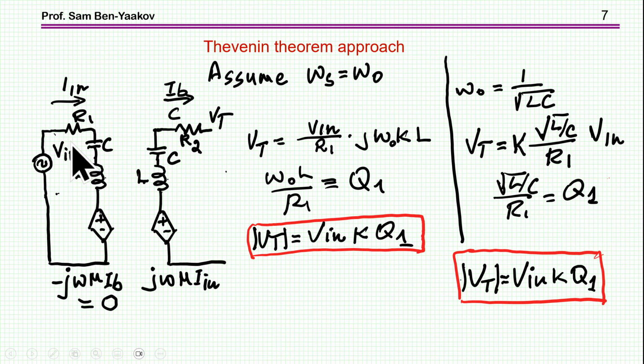Now that we have this equivalent circuit, we can actually simplify methods quite a bit by using the Thevenin theorem, which means that we can represent the whole thing as one source and one internal resistance. Now to do this, I'm first of all finding the open circuit voltage here.